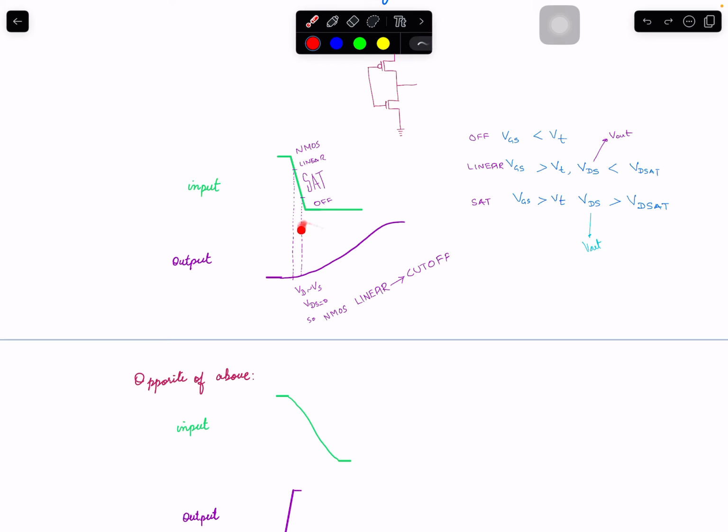But why is this not good generally? Even though it's good for short circuit, this kind of circuit will be delaying things a lot on the next stage. So the delays from this one to other stages will be huge. We don't want to reduce power at the expense of timing or creating more timing problems. So not a good idea.